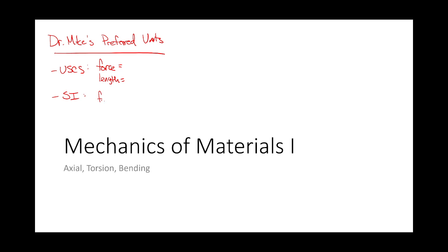If you've ever done any type of finite element modeling using any advanced software and whatnot, a lot of times you'll find that those software programs are unitless by nature, and you kind of have to establish this right off the bat. And I think in mechanics of materials, you kind of need to start right off the bat, and I think that this can serve to reduce errors moving forward. It's not always necessary, but I would argue that if there's ever a situation where you're going to see the need to do a lot of conversions, I would convert to a consistent unit system.